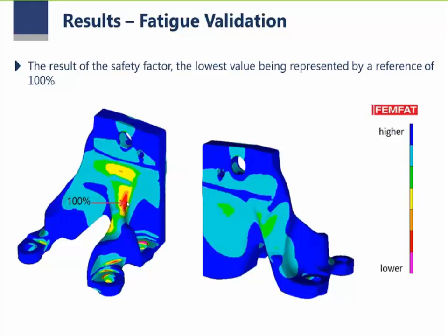There's just some part here, and here this is a stress concentration for the bolt. Also, there is some radius here, but this part is more critical than here. This doesn't mean that the component is failing. We are just using the colors to say that, for example, here we have 100% of the safety factor.